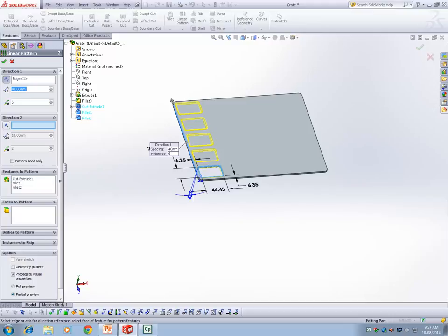You can also draw now in a new direction. Select a Y direction here. Once it is selected, say if we have added 2 patterns, you can change the direction, which should be opposite, and increase the distance here. So this is where a linear pattern in another direction is added. But if you don't want to select the pattern already created, this is a pattern on top of a pattern, you can avoid that by using the pattern seed only.